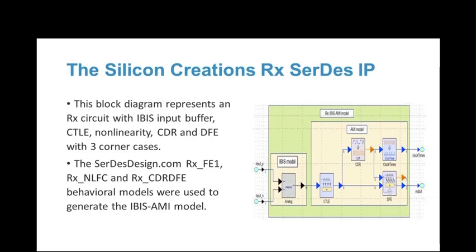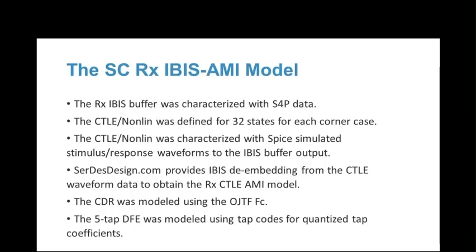A behavioral model for this circuit was created with the 3 corner cases. The SerDesDesign.com behavioral models for front end, for nonlinearity, for CDR and DFE were used to generate the IBIS-AMI models. The CTLE in the receive circuit was inclusive of the receive input IBIS buffer and was treated as a black box with stimulus response waveforms.